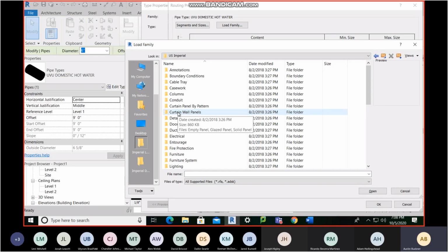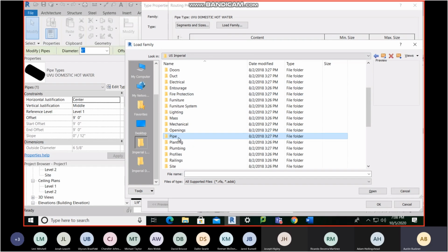Now, if you're working with some specialty system, you can go online and find it and bring it in. People have created those. If you're working with a specific client or manufacturer and they want that shown in their model, you can go to that manufacturer's website and download Revit families, if they're used often enough that they have the ability to BIM out their fittings. They'll have those.